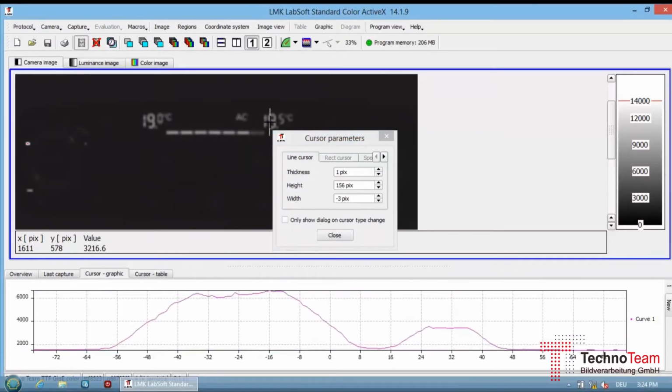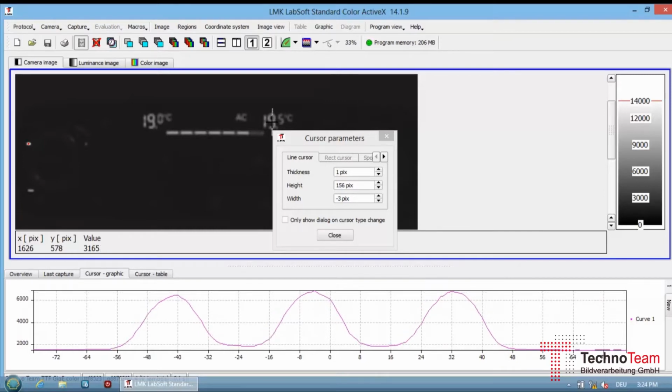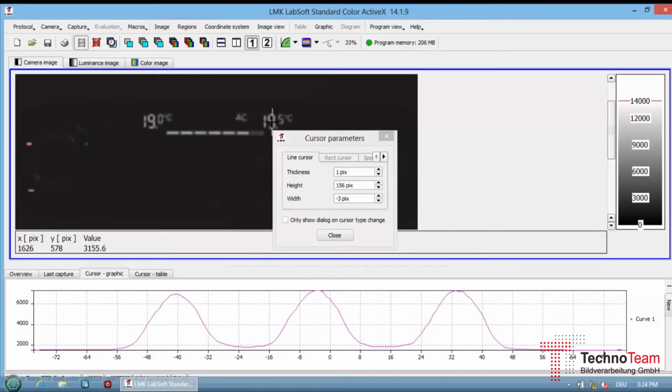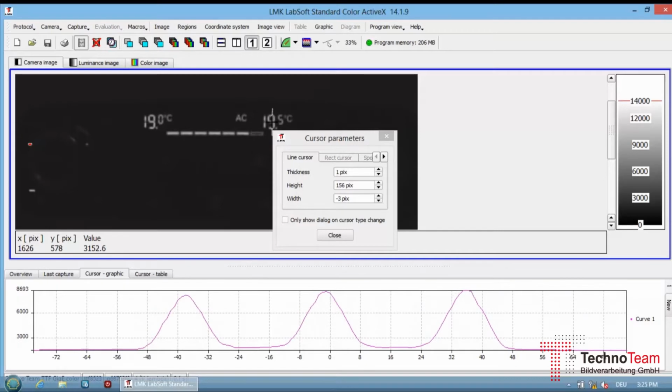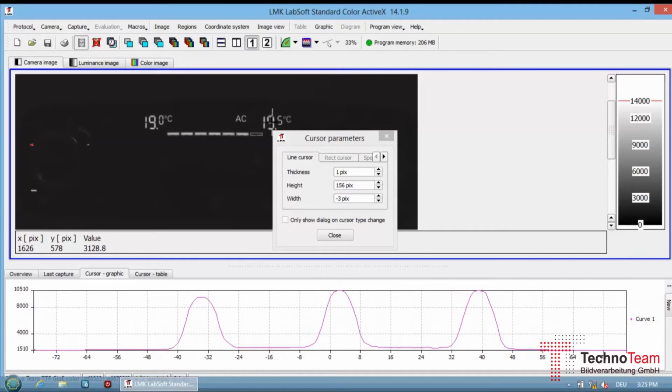The diagram at the bottom shows the gradient and maximum value of brightness depending on the set focus of the lens. The aim of this focusing procedure is to maximize the pixel space shown at the x-axis. Also, a resulting aim is to maximize the brightness level at the y-axis. The unit at the y-axis is digital grayscale.